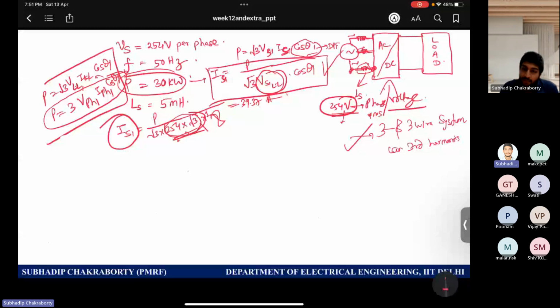So to determine the harmonic voltages, because you know how the PWM voltages look like, it is a square wave. For a square wave, we already studied that if we know the information about the fundamental of the square wave, we inherently also know the information about the other harmonic components. So if somehow we can determine the amplitude of the fundamental or have some information about one of the harmonic components of the square wave sitting at the inverter nodes, where the PWM voltages will appear like pulsed square waves.